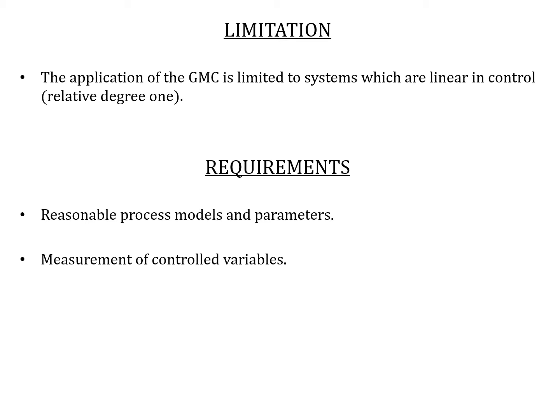So there's that limitation. Not everything can be done, which is why it's relative degree 1 when you talk about nonlinear differentiation. When we differentiate on the first order, the U should come out visibly, so that we can use it immediately. If it cannot, then it's not relative degree 1. We may have to differentiate again as relative degree 2 and so on, which no longer applies for the GMC method. So this is a limitation.